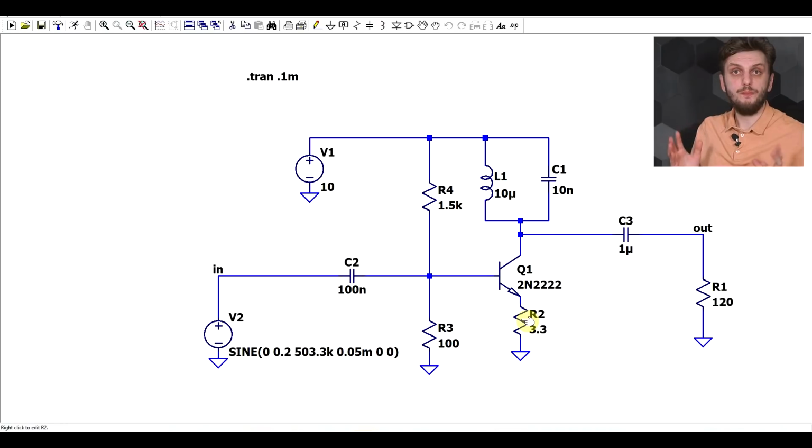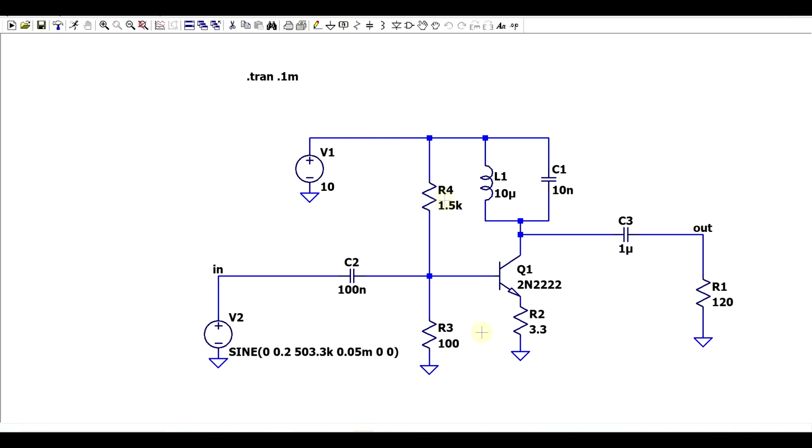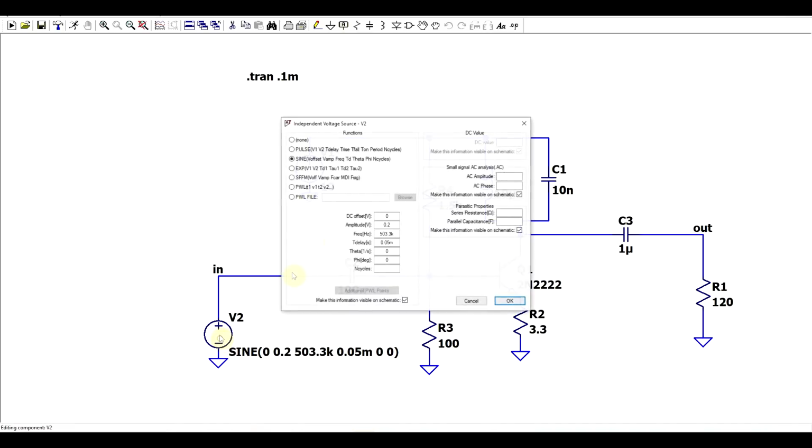Now, as previously stated, the class B amplifier amplifies half the signal. What about the other half? Well, there are multiple things that can be done. In the interest of using a minimum number of amplifying elements, one method of providing the missing signal is by using a high Q-factor resonance circuit. So, what I have here is a circuit that looks like a typical class A amplifier, using a transistor in common emitter amplifier mode. So we got our emitter resistor, a voltage divider to bias the transistor, but to test it out, I specifically set the input signal to have an initial delay.